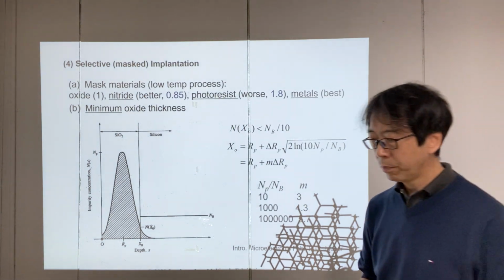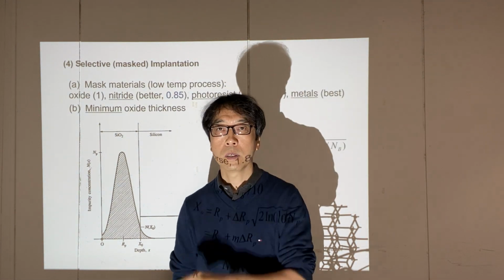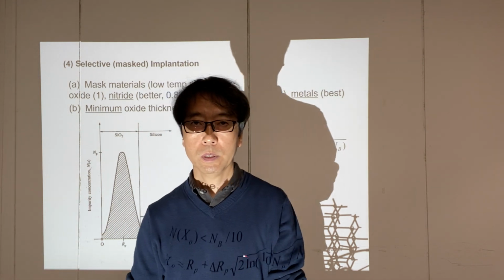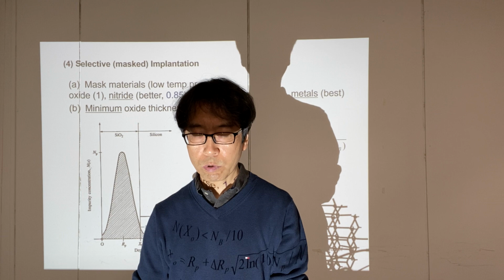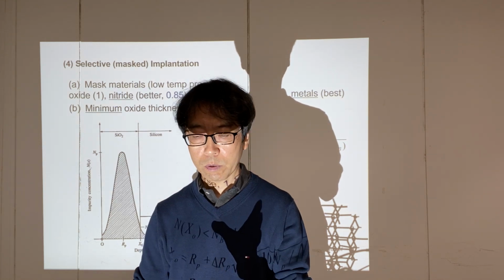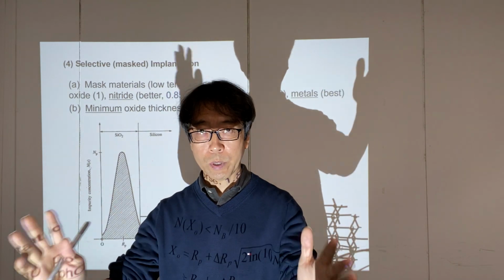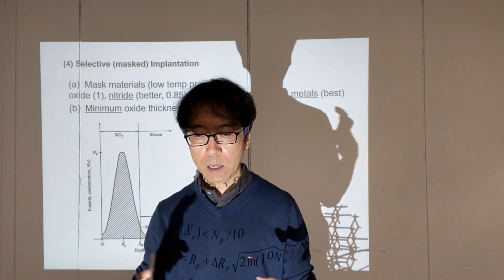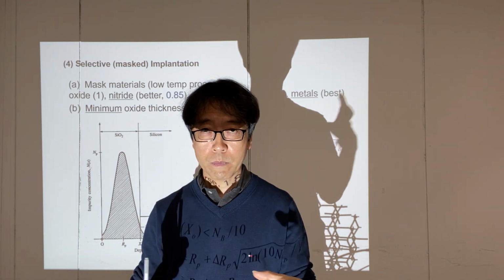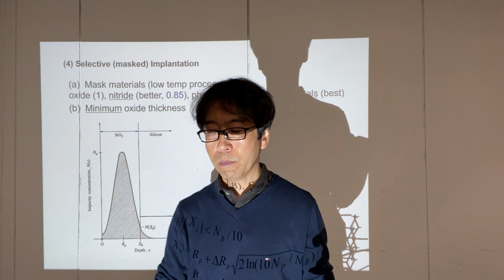So the beauty of ion implantation is we can mask out the area. In other words, we can try selective doping. We just have a thick film and then an opening, and whenever there's an opening, such an opened shape will be exposed to this bombardment of impurities.